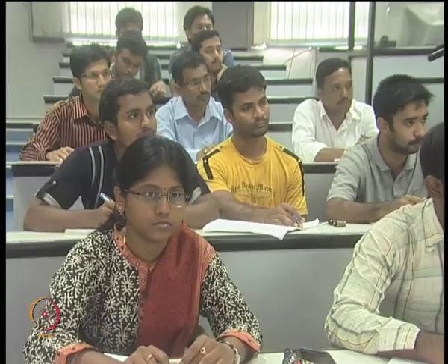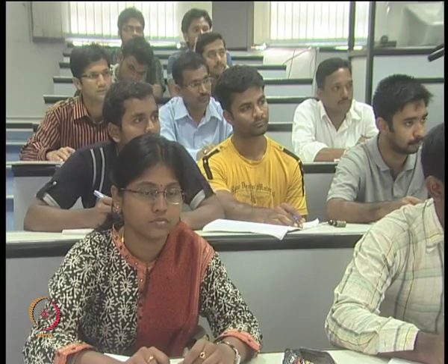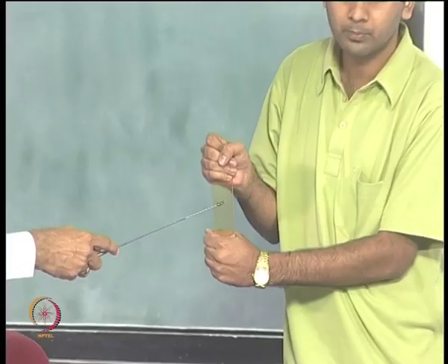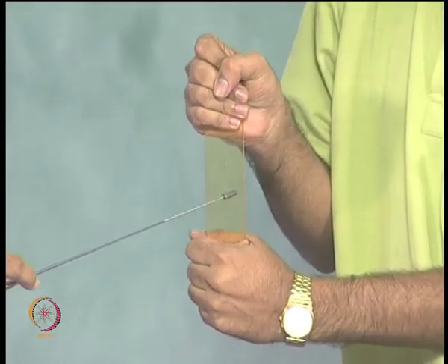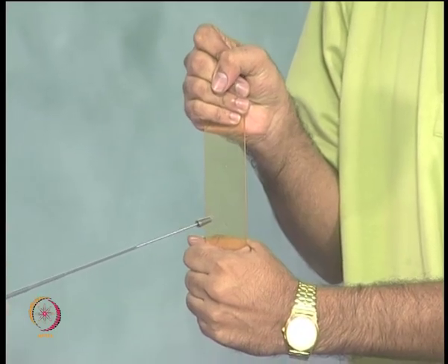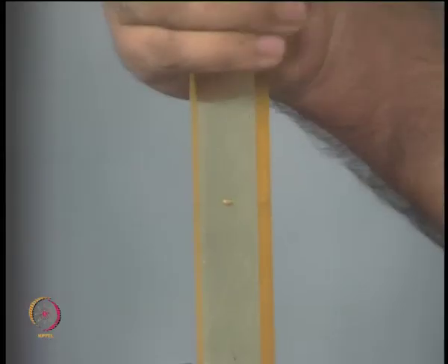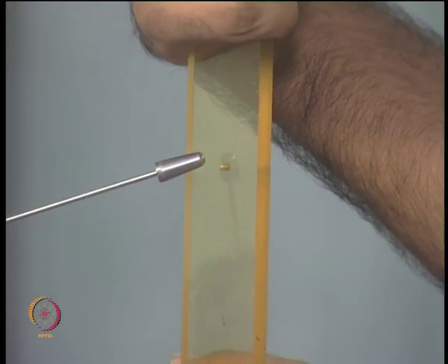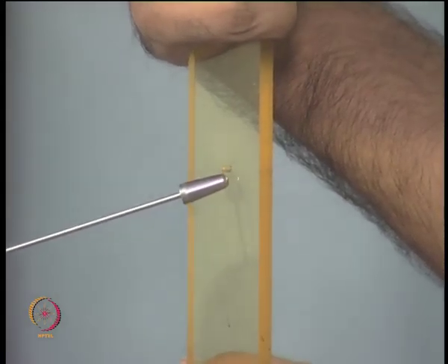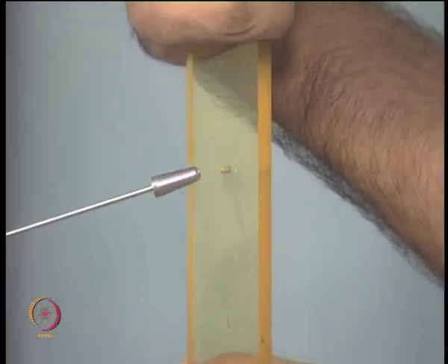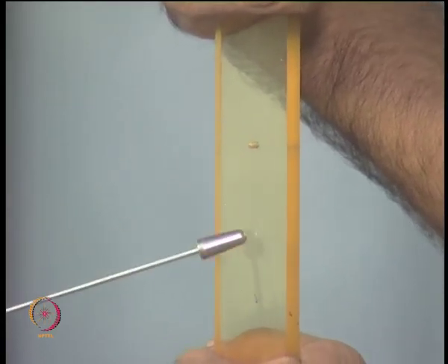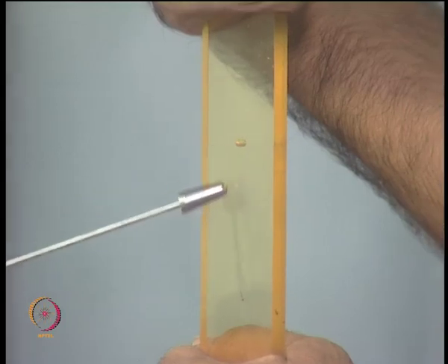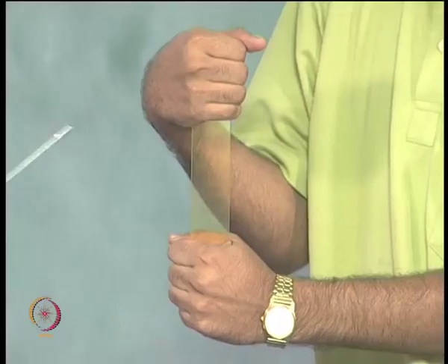However, you can still attempt to solve by theory of elasticity if the hole size is very small like this. For the same width of the member, if the hole is very small, though physically this is a finite body, from a mathematical sense this could be considered as at infinite distance away, and you could invoke theory of elasticity solution and then get a closed form expression. So, the size of the hole is very small compared to this.